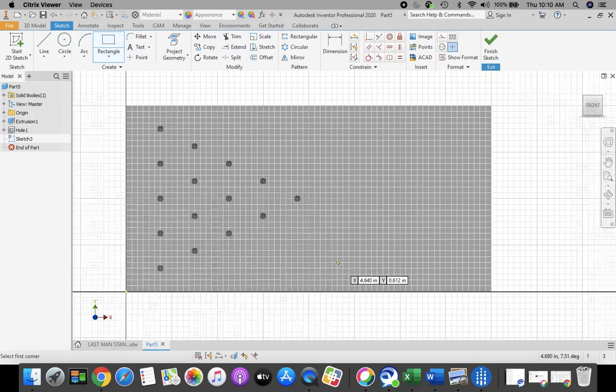We're going to click, and we're going to stretch out a rectangle. The horizontal dimension for that rectangle was 1. Type 1 on your keyboard. Press the tab key. My vertical dimension for that rectangle was 3.5. Type that in and press enter on your keyboard.